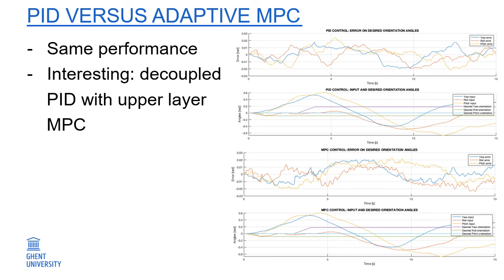If we check the performance of PID and MPC separately, we see that performance of both are similar. This can be seen from the error on the orientation angles. The MPC is computationally more expensive but takes into account the input constraints. Possible grounds to be explored are to apply a PID first and an MPC afterwards. This idea was also explored in computer control of industrial processes.